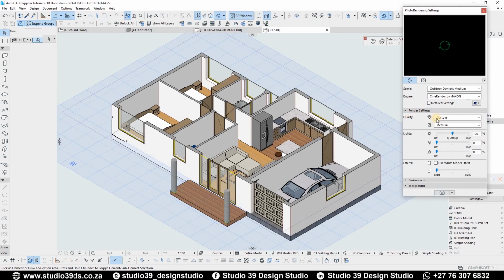And then you can set up qualities. Qualities, you can make it sharp. Let's make it medium for this one. And the shadows, they're going to be medium right now. There's other settings you can set for that. And under lights you have the sunlight, you have the lights which are sort of like the lamps' intensity, and then also the illumination surfaces intensity. That's something that I'm going to go into at a later date.